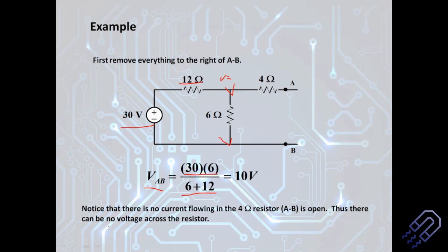So what happens here is that if you have a circuit which has got a number of resistances, you can find out the total resistance, put it at the bottom, and then take the voltage of that particular circuit, multiply it with the resistance across which the voltage drop has to be measured, and then do the calculation. This is actually very important if you want to do some sums fast. So you just do this calculation. This will be nothing but 10 volt.